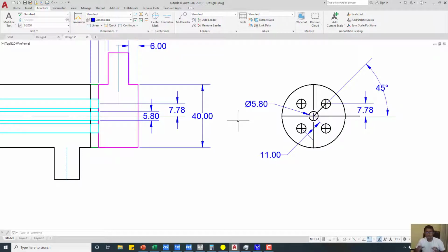That is through the effect of the single tube and then on the 5 tubes. So what will happen with the heat transfer and as well as the pressure drop, because pressure drop means that we need more pump work, that is the energy input we are giving, and better heat transfer means that we are making the process complete within the given size of the heat exchanger. So these are two design constraints, and they are opposing constraints. So we have to make a compromise between these two design variables.